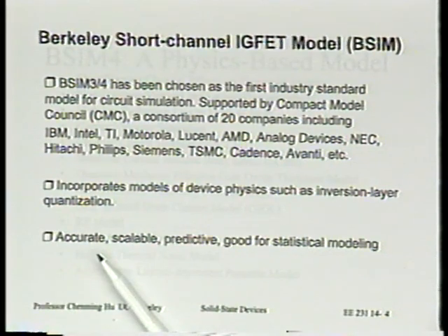But you take a model like that, accurate or not, and just put in many parameters. It doesn't matter if a parameter really corresponds to the measured mobility or not. We consider everything as fitting parameters. Then we compare this model with the measured IV curve and try to adjust the parameters until they fit. It doesn't matter whether the mobility is real mobility or the resistance is real resistance or not. We'll just do that.